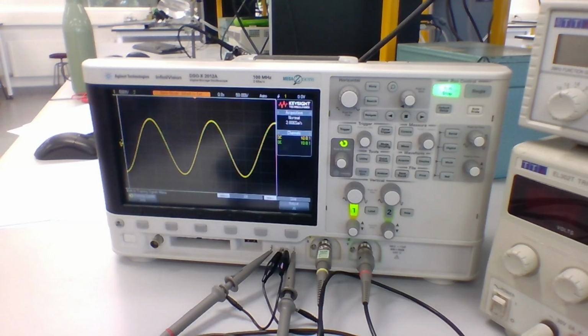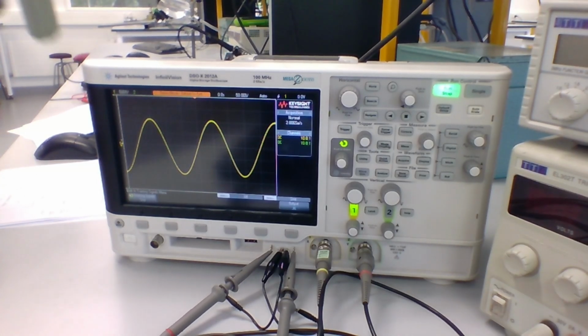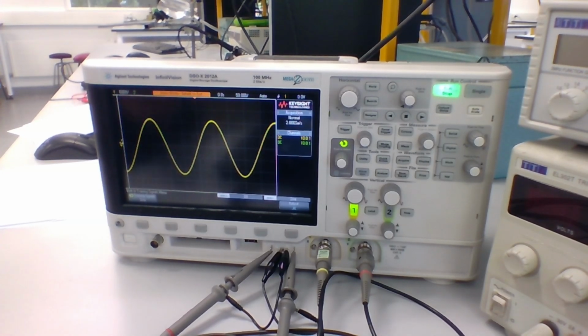So when the oscilloscope takes measurements, it does so using what's called a trigger. Basically, the oscilloscope needs to decide when to take a measurement of what is going on. It's measuring some continuous signal and needs to capture that so it can then process it and display it on the screen, and it needs to know when to do that. That is decided by using what's called the trigger.